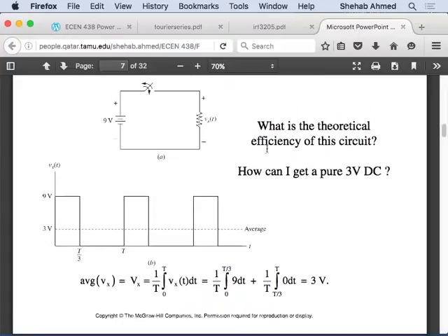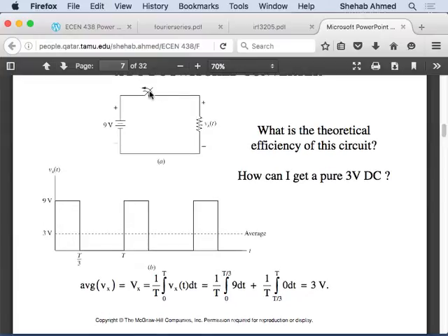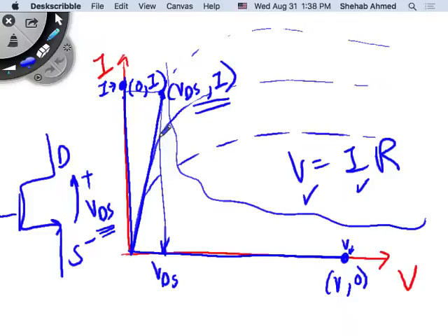So we went here from something that has ideally 100%, and I think, do we all see why I say the switch will have ideally 100%? It's because I was operating on these two curves here. If I'm operating on the real curve, then the switch will have some resistance when it's on, right? But is this value of resistance big? If it's big, then the voltage will be big, right? Because I have it for a certain value of current. If it's small, then the voltage will be small. I'm operating on a very narrow part of the device's characteristics here, right?